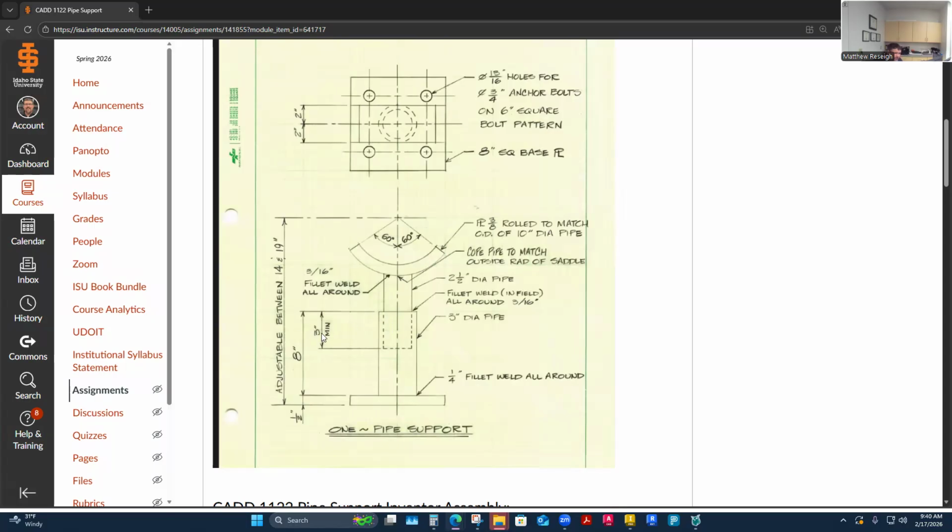This is a critical dimension, and I'm trying to maintain that. So I'm already building that into my part before I even start drawing it. I'm already building where it lives. Since I've derived in that other part to work from, I'm going ahead and establishing a plane that isn't exactly where those two parts come together. So that's where my plane is now right here.